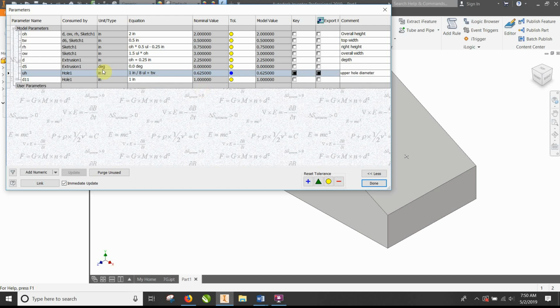As you're seeing, you're going to have to update this often because you're not going to use these variables D11. Notice it skipped around. It went to D11. And Inventor is going to do that. So you need to standardize your variables. All right, because it's not going to go in order. Okay, it is going to jump around. So for example, this right here is the depth of the upper hole.